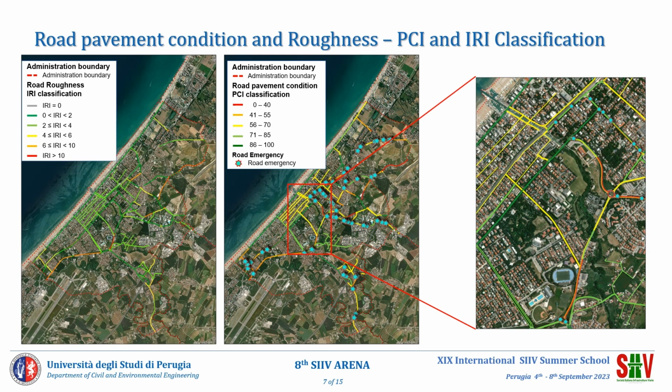For the evaluation of pavement roughness, the International Roughness Index (IRI) was measured on specific routes using a selected application for smartphones, while for the evaluation of pavement condition, a rating system was defined considering a standardized visual inspection method. The Pavement Condition Index (PCI) was calculated on several pavement segments to create a reference scale and address the classification of inspection units by comparison. Also, road emergencies in restricted areas can be reported using a GIS mobile service.